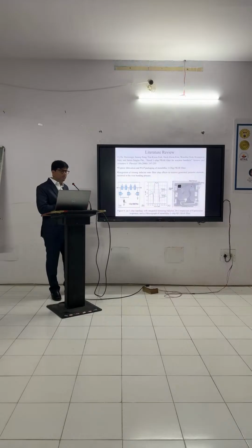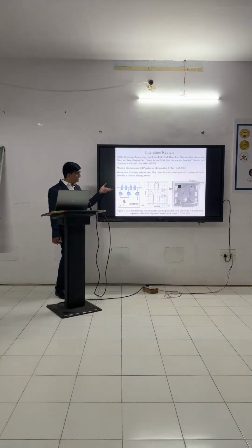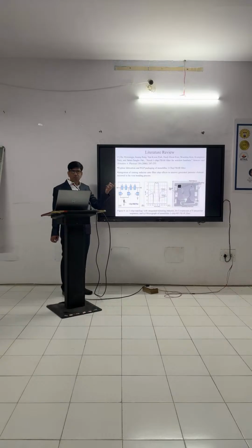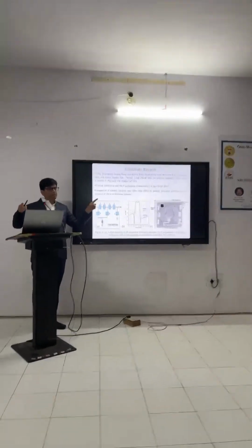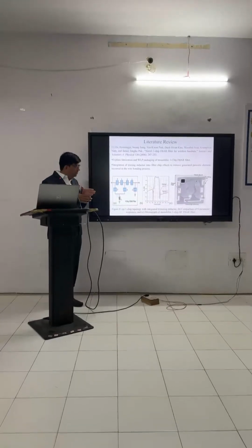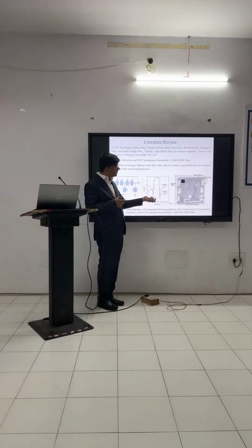Okay. So first we have an application of this acoustic resonator to design a filter. First we have to optimize my device, and I can use this device structure either in the ladder type, pi type or L type. Clear? And here we have two types of frequency. The anti-resonant frequency of the series resonator is equal to the resonant frequency of the parallel resonator, so that we can design a particular type of filter.